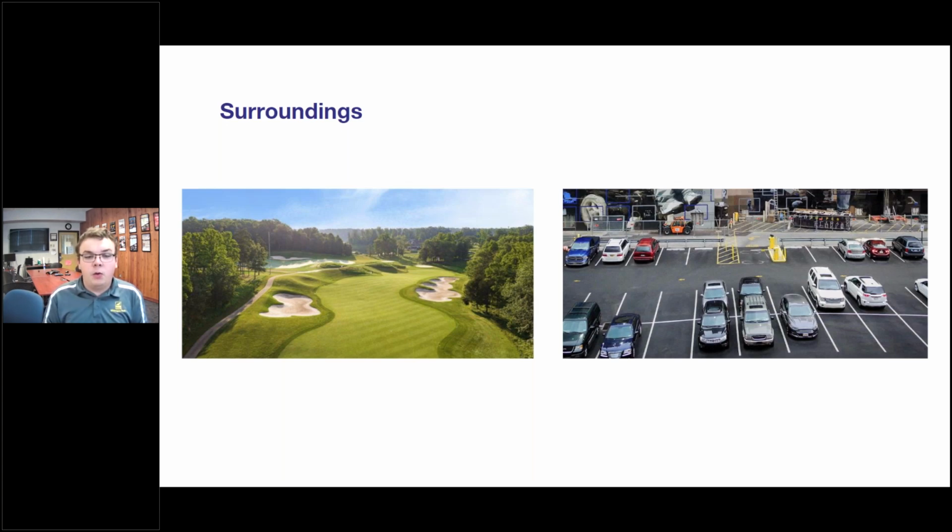On the other side of that coin, if you have a lot of impervious urban area around you, or for the system that you serve, if it rains, that's going to pick up all the brake dust, gasoline, oils, sediments that are all on the asphalt, and it's actually not going to get that infiltration like you get on a normal soil surface. Then you're going to get far more amounts of rainwater entering your system, as well as just more heavy metals, more arsenic, that kind of thing, if you're having that problem with your lagoon system.